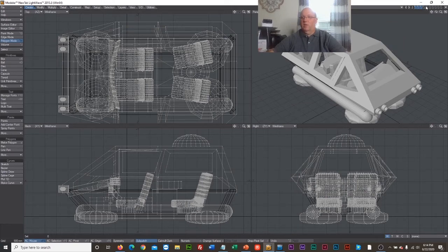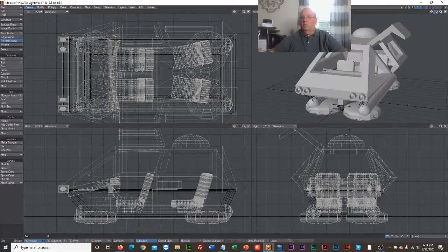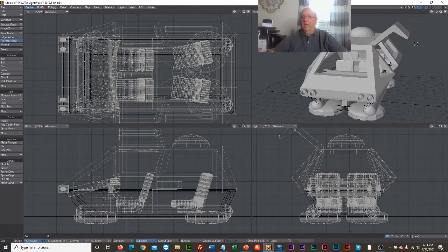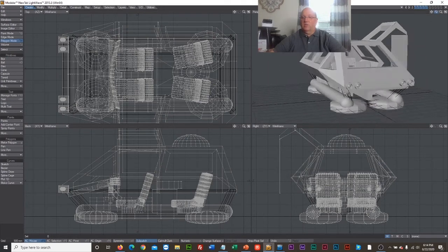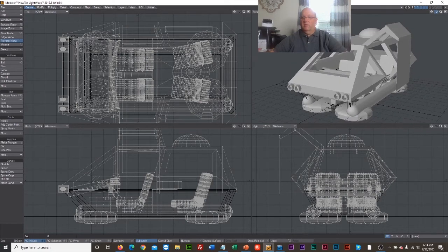I'm going to turn that off for a minute, and I'm going to put this on. This is the door in the open position. I wanted to print out this door in the open position. Now the problem is, if you're 3D printing, it starts from the bottom and works its way up. And so that means that aspects of this are flying out in space. So I created this very thin wall to allow the 3D printer to build some plastic to base this on. And so that's one way of doing it, and that's how it worked. And it actually did work. Okay, so this was a very small print that was never actually designed to be seen in great detail.